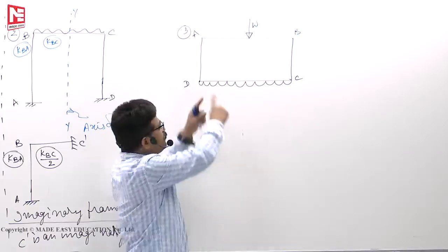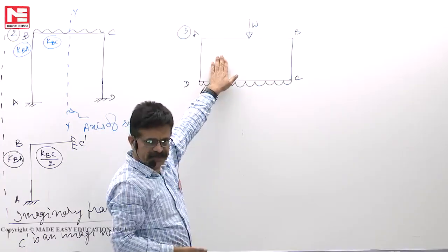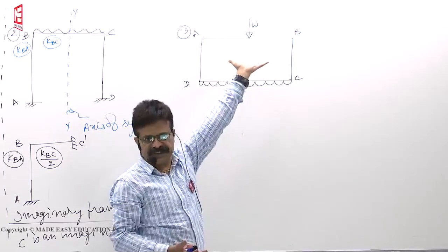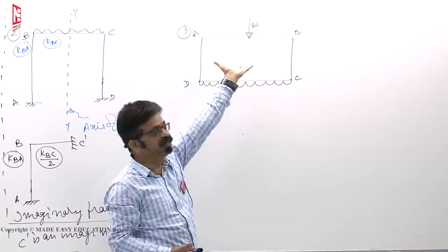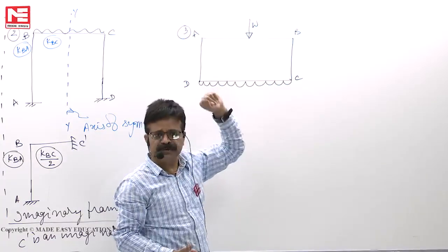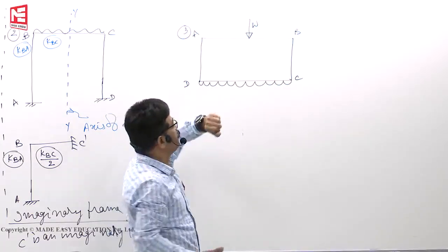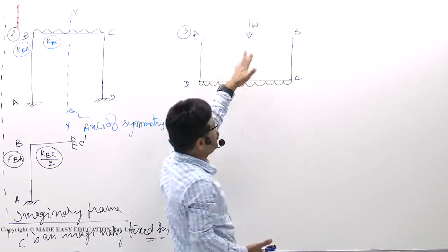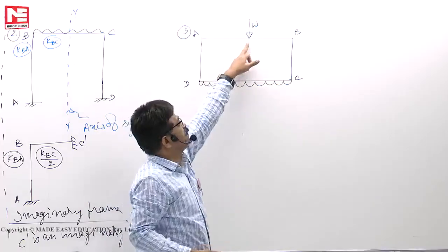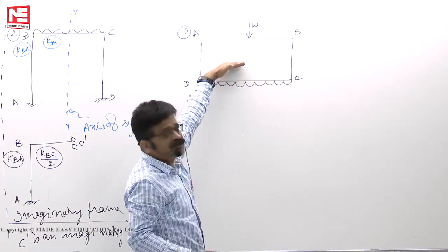Same thing here. This is a tunnel, maybe you can take like that, it is resting on the ground. This is upward soil pressure, uniformly distributed. Downward there may be point load or there may be UDL also, whatever may be the type of loading. Okay, so this one box frame you have taken. It can be water tanks also resting on the ground. In such cases this will not be there. It is filled with water, let us say.